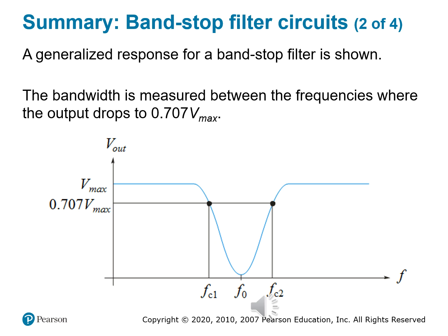The region is specifically rejected while everything outside of it flows through mostly unaffected. And this matters because this is incredibly useful when you're trying to eliminate power line interference at some specific frequency, if you need to silence a feedback loop in audio systems, or if you want to, let's say, surgically remove narrowband RF noise.